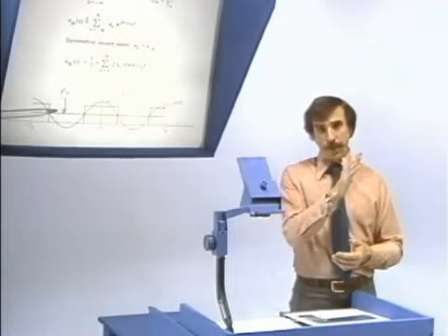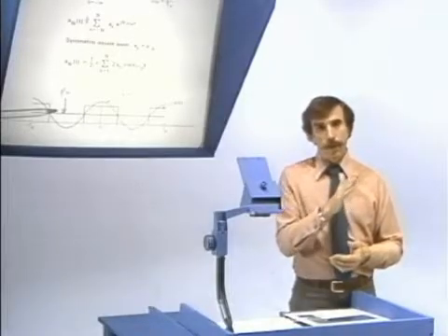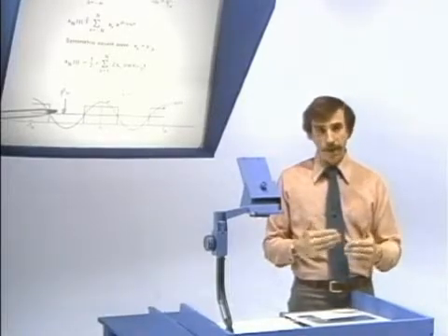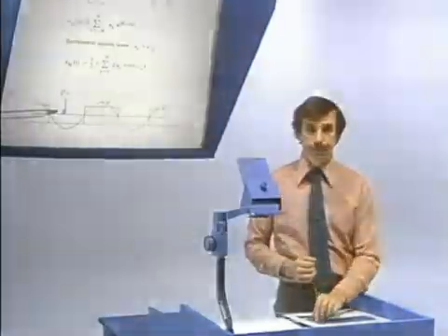And what we'll see is that the energy in the error will be tending towards 0 as the number of terms increases. So once again, we have the square wave, and we want to again show the buildup of the Fourier series, this time showing also how the energy in the error decreases as we add more and more terms.